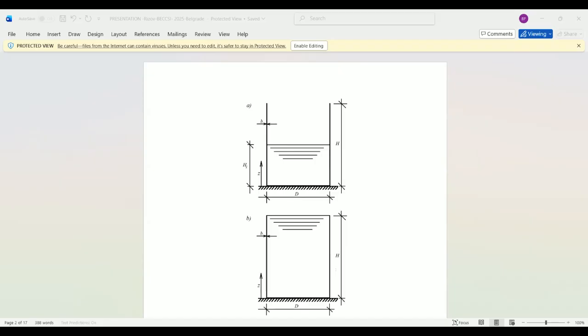The viscoelastic behavior of the tank wall in the process of filling up and running off is treated by using a nonlinear stress-strain time relationship that accounts for the stress history. This relationship expresses the total strain as a function of stress and time.